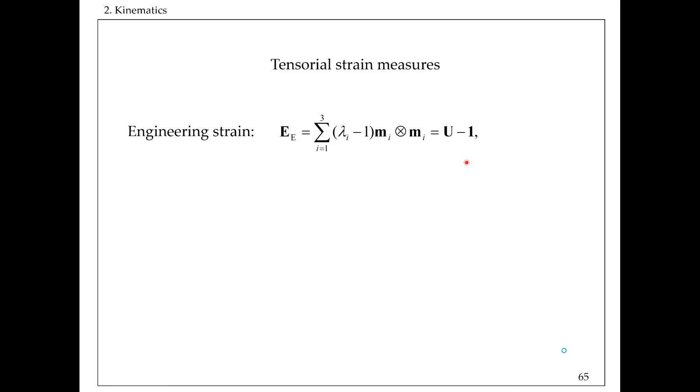So that's where our knowledge about the tensor functions will become handy here to introduce it in an effective way. Basically, we are not applying that logarithmic measure on the basis vectors of this tensor product, but rather only on the scalar function lambda, the stretch, and so we can write it as just ln U. So the logarithmic strain is applied to our right stretch tensor U.